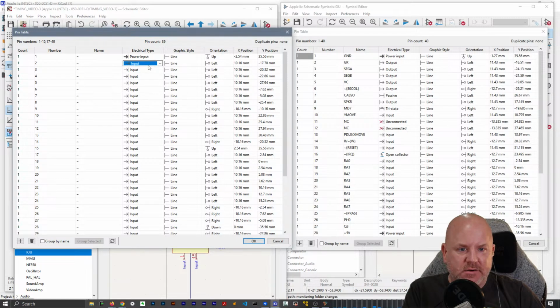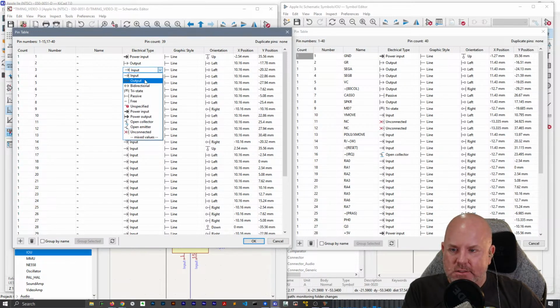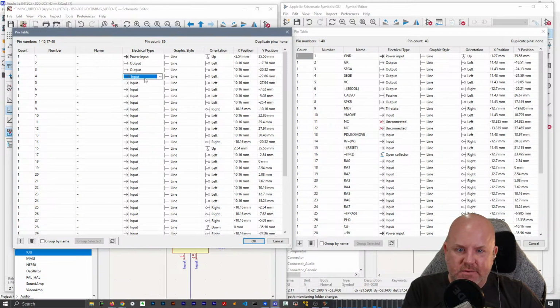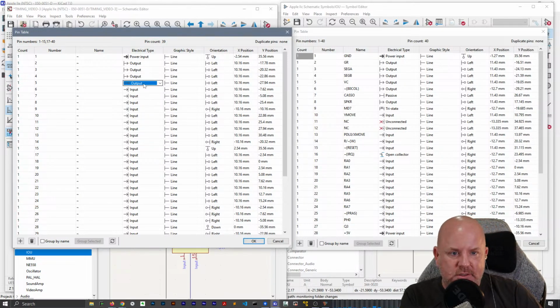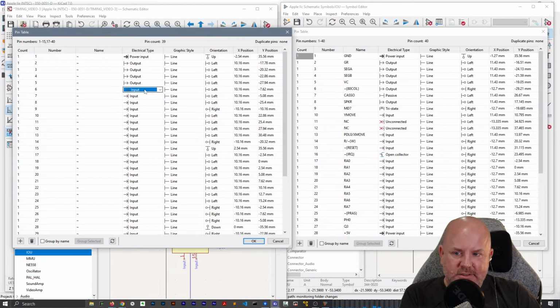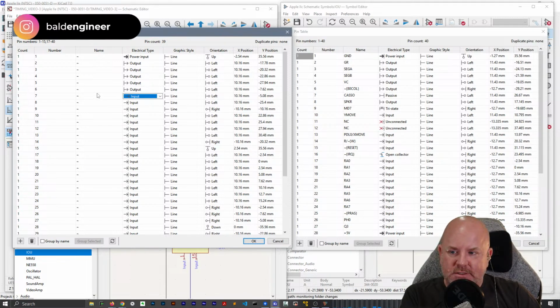It's the cassette interface pin that got repurposed in the 2C. Since the 2C doesn't have a cassette interface, that pin now does the bank switching between the two ROM banks. Yeah, so like pin 7 is... I wonder why I marked it as passive.